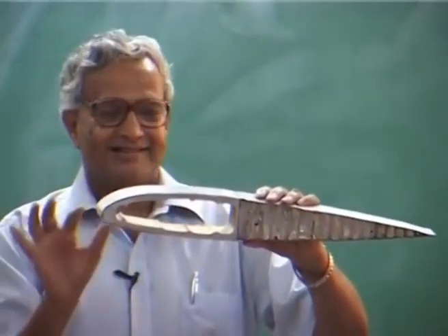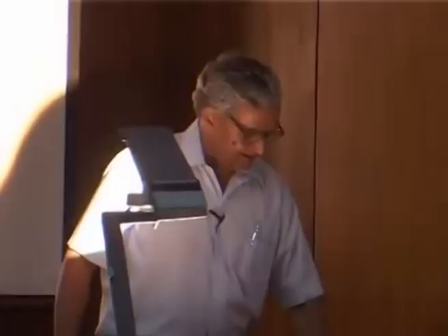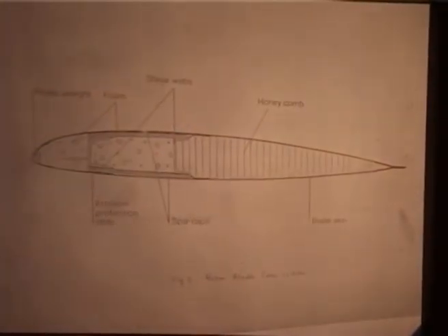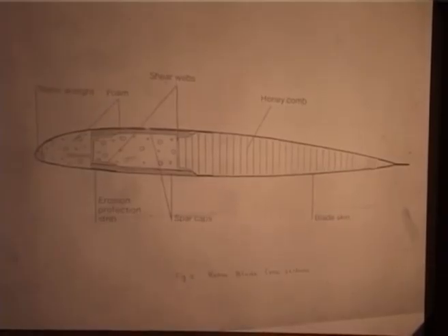So, this whole design is made in such a way that, I will show a typical section of a rotor blade cross section, just similar to this. Okay. Only thing is each blade has its own section. This is the real life actual blade cross section. You always put a leading edge weight, that is to shift the center of mass to 25% chord from aeroelastic considerations. Okay, we will learn that.